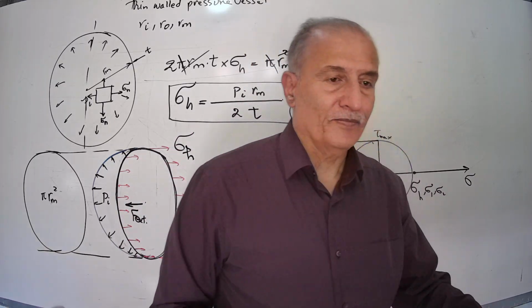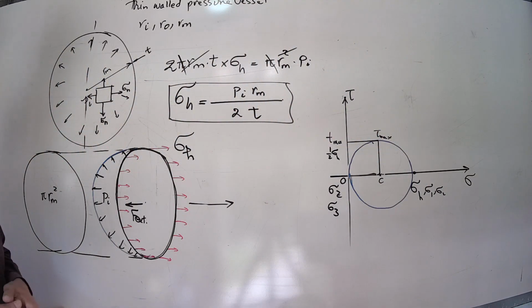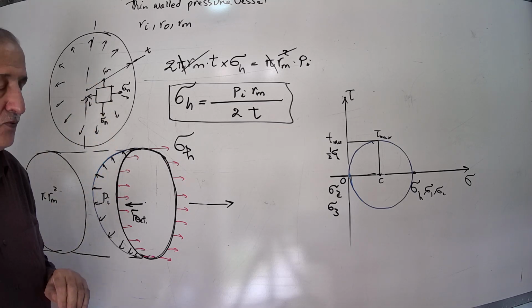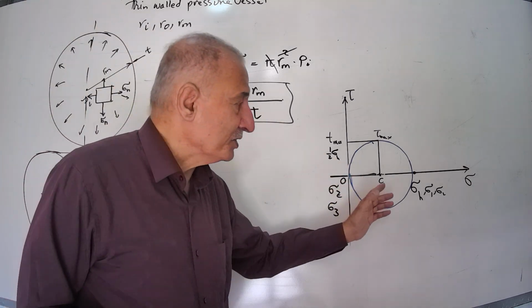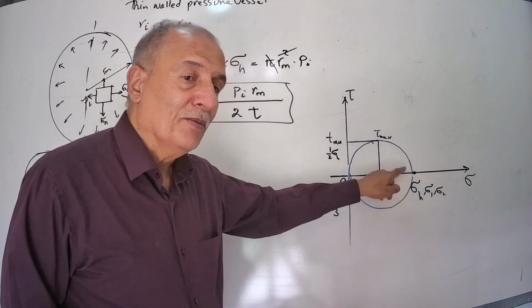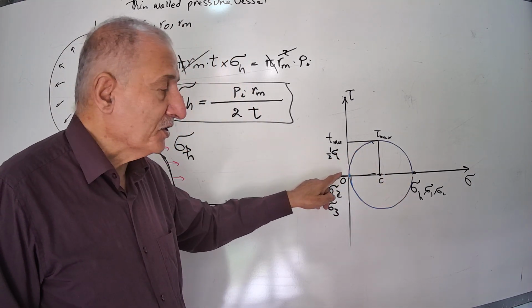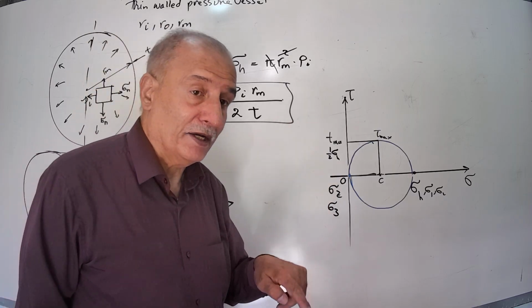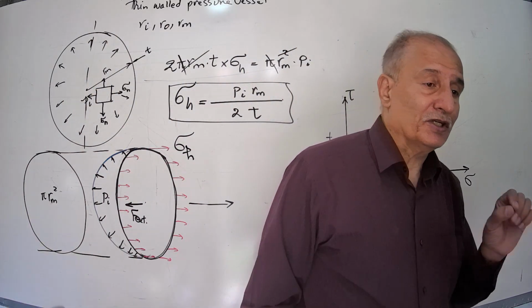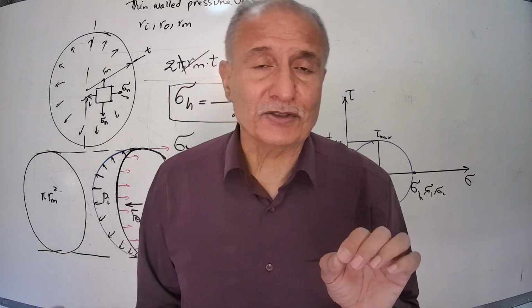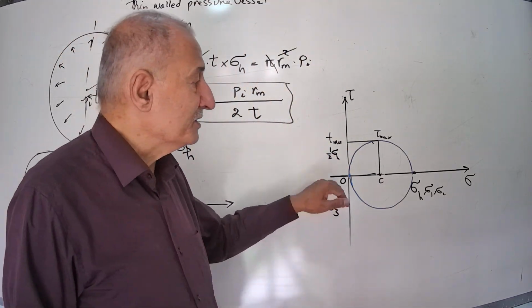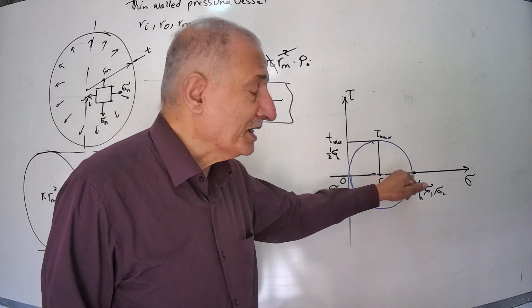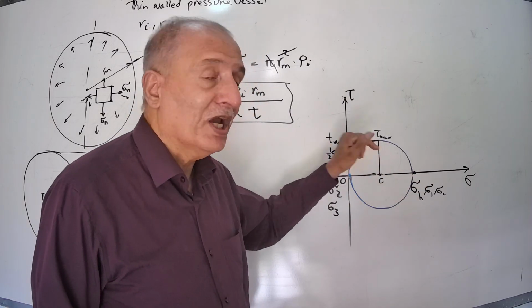That's the Mohr circle for a spherical shell, plane stress, where both stresses in x and y are equal, and the two-dimensional Mohr circle reduces to a point. But because there is another stress, sigma z, in the thickness direction of the shell, whose value is 0, we must consider it, because the difference between 0 and the maximum stress produces a shear.